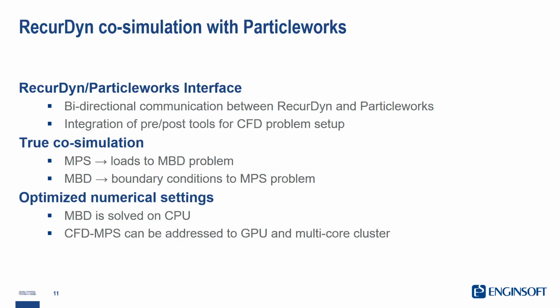So the integration is already in place, and it's very easy to set up a coupled simulation between RecurDyn and Particleworks, and we can integrate pre and post tools and so on. What happens is that we have a transfer of loads from the MPS, the moving particle simulation, that is the CFD Particleworks simulation, to the multibody dynamics problem. And the multibody transfers the boundary conditions of the walls to the MPS problem, so the CFD problem.